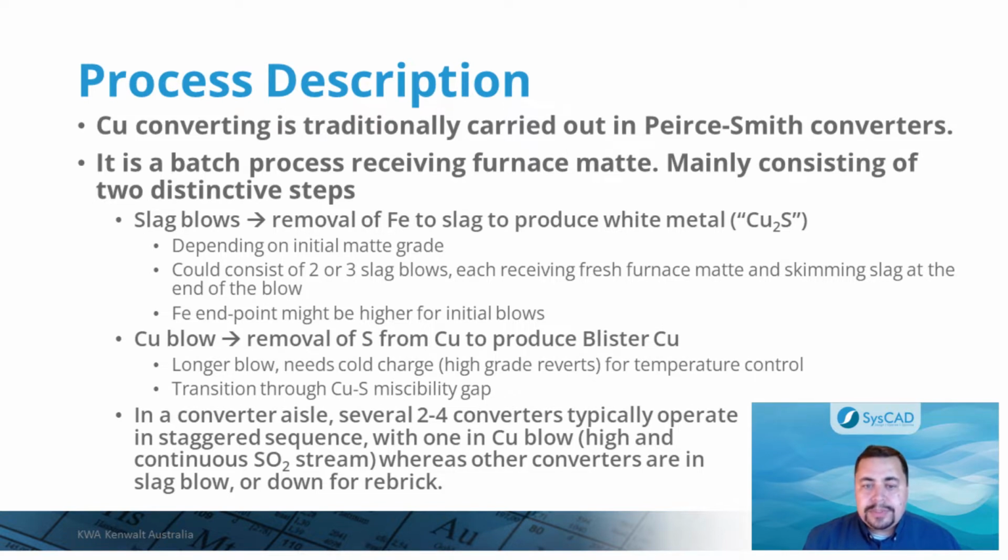There is also an important consideration from the thermodynamic point of view, which is the pronounced non-ideality of the system. In particular, the presence of a miscibility gap near the copper-sulfur binary, separating the sulfur-rich matte from the blister, which results in the coexistence of two liquid phases during most of the copper blow. This added thermodynamic complexity and the time-dependent nature of the process makes the use of the combined SysCAD plus ChemApp tools the ideal approach to model this process. The contents of the converter are assumed to be at chemical equilibrium at all times.